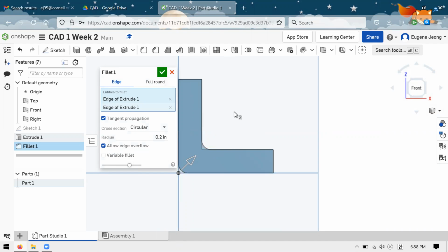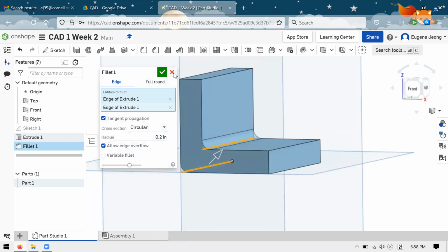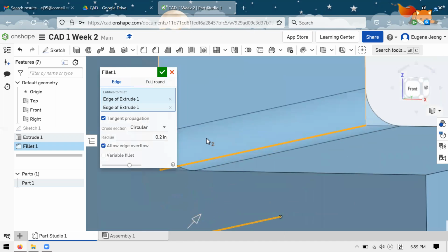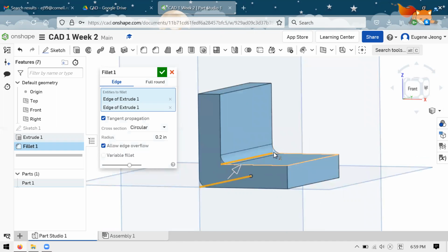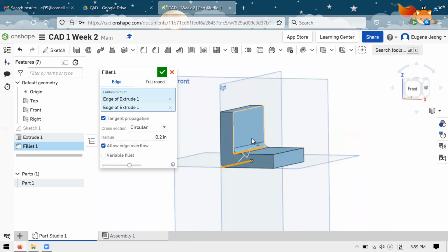And the third reason is that when you're designing things, it's actually a bit stronger to have these rounded off corners because it avoids something called a stress concentration, where at these really angular geometries where your part comes to a point, it's actually going to create a higher stress at that point, making it more likely to break starting at that corner. You can imagine the part might be a bit weaker at that corner. So making the smoother transition between surfaces can help with that.